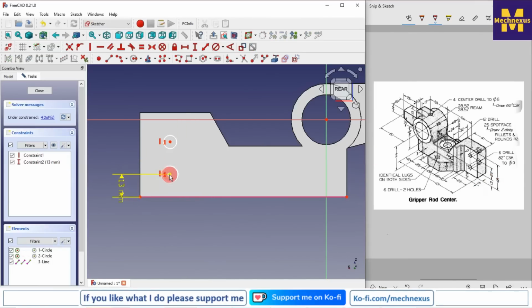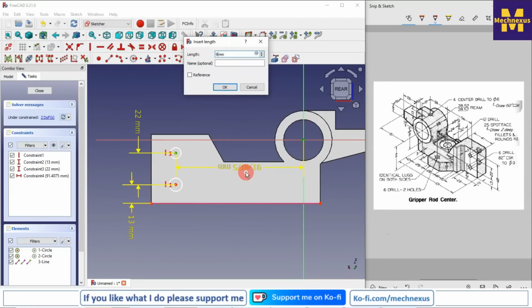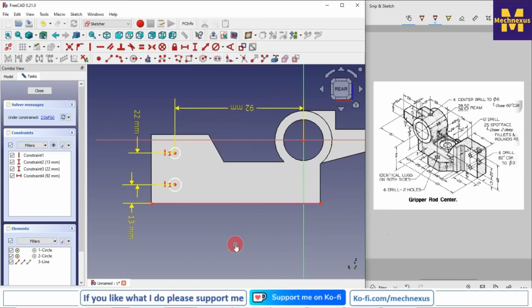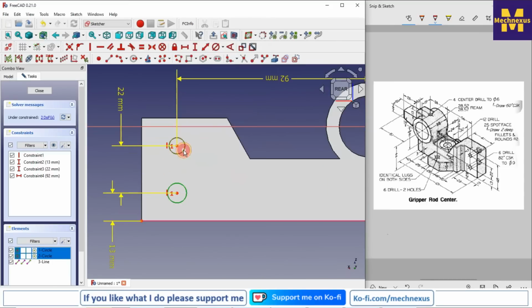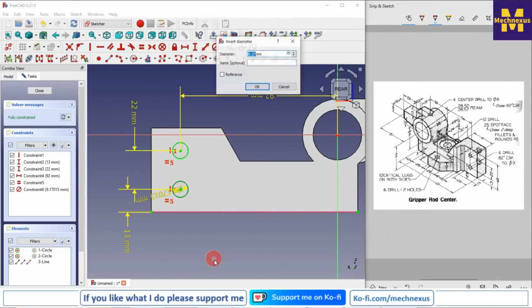Center to center is 22. And from the center to this hole is 92 mm. So I will give the 92, and this circle will be equal, and it is a 6 mm drill, so I will give it a diameter of 6.